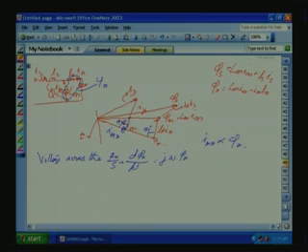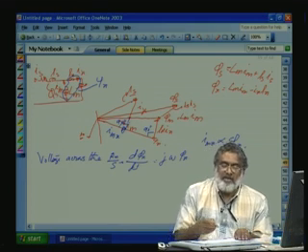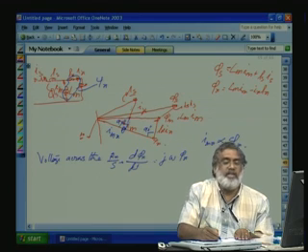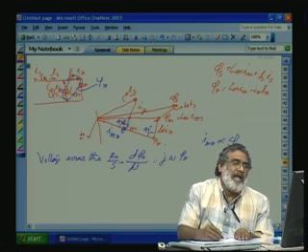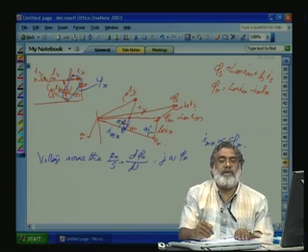If we find an equivalent circuit based on this, then that is the equivalent circuit required for high dynamic performance drive application. That means we have to keep varying this IR, which is perpendicular to IMR, during the torque production, and this IMR we have to keep constant, so that psi r is also constant. So, there is a decoupled control possible in the same way as in a separately excited DC motor.